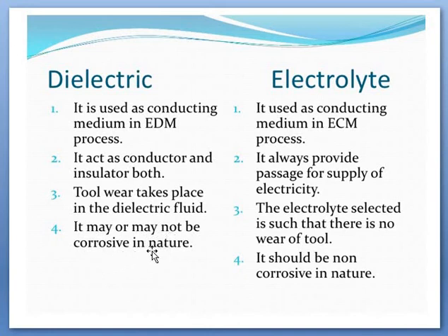A dielectric may or may not be corrosive in nature, but the electrolyte should be non-corrosive in nature. In the previous slide, in EDM we use dielectric as a conducting medium, whereas the electrolyte solution is used as a conducting medium in ECM. What is EDM? Electric discharge machining. And what is ECM? Electrochemical machining. Are you getting these points?